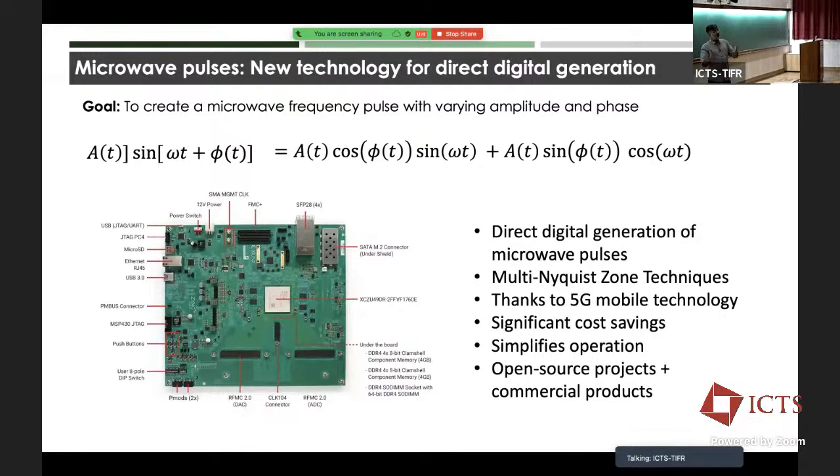Most of you who have learned about digital to analog and analog to digital, we learned this thing called the Nyquist criteria, which says that if you want to digitize a signal of frequency f, you have to sample it at least at twice that frequency, right? The simple picture being you have a sine wave, you at least need 2 points per sine wave to at least have some resemblance to the original waveform.